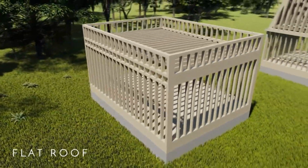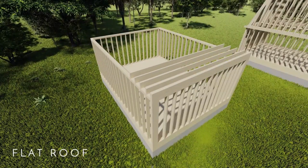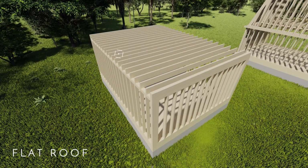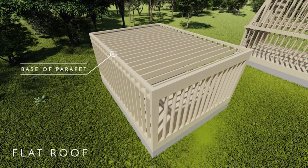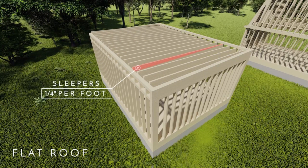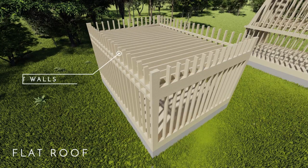Alright, so next up is the flat roof with a parapet. So in the case of the flat roof, these actually aren't ceiling joists, these are called roof rafters, because this is the actual roof. Then the base of the parapet is laid out, and something called sleepers are laid on top of the roof rafters. And what a sleeper is, basically, is a wedge of wood. It's kind of like that block of wood that you put in your door as a door stopper, to give you an image. Alright, so after that the parapet can be framed.